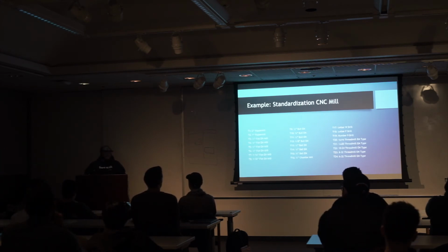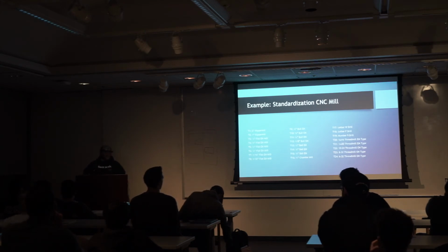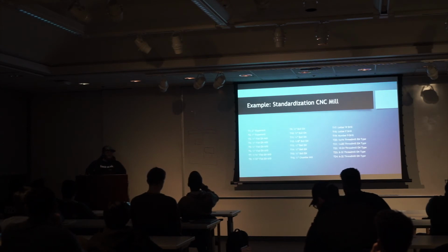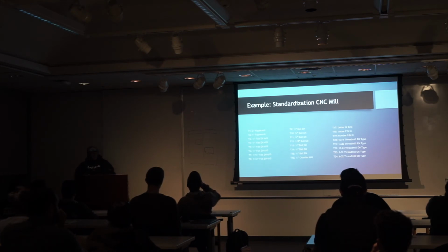And it all came from the tool. So my standard was 4 times the diameter of the tool. I multiplied the radius by 1.5, because when you're milling into the corner, your forces go up. So there was a reason behind it. It wasn't anything super special.